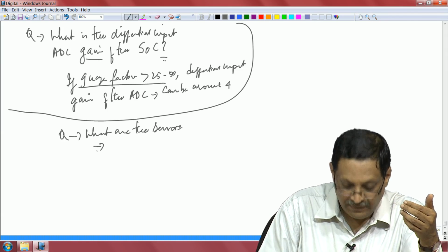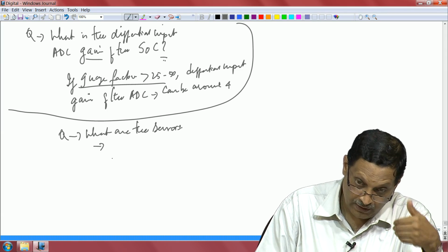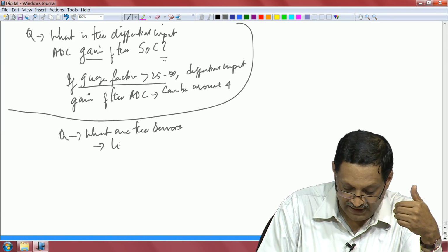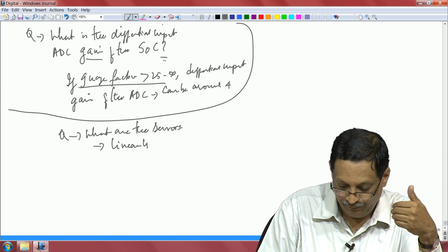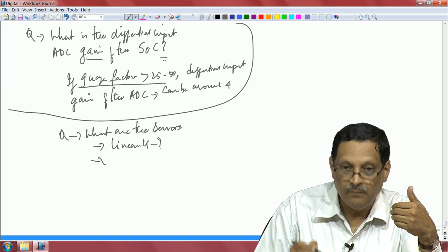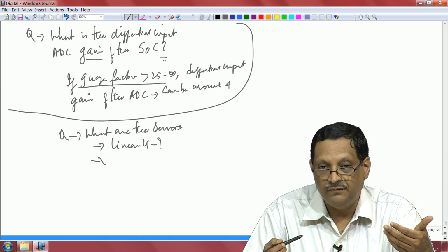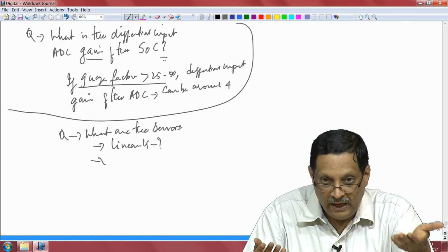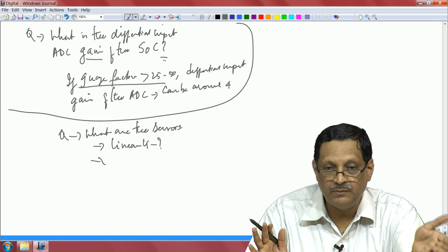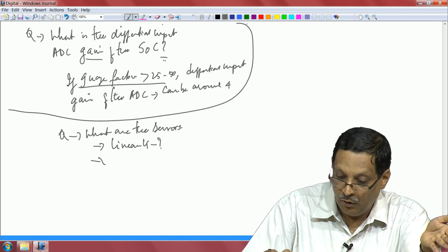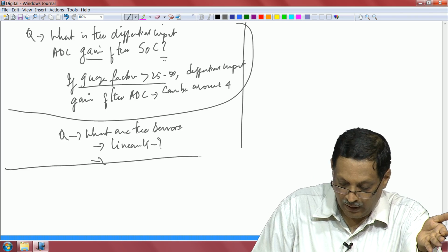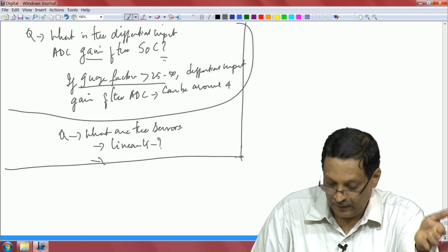What do you want from these sensors? Do you want them to maintain linearity, and if so, how will you configure them? Will they take differential input? What is the gain? Okay, these parameters have to be borne in mind to choose a microcontroller.